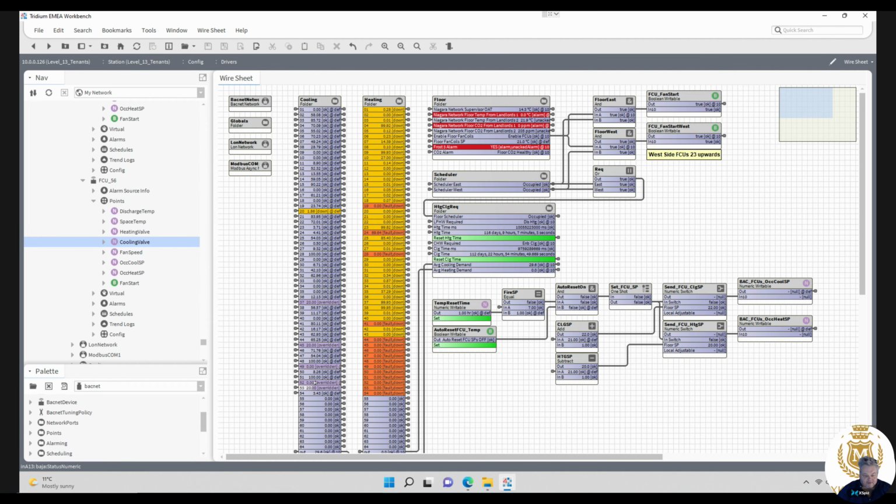And we can see that they've got some overrides, they've put some overrides in themselves. That one was down, so we know there's an issue there, and you can see now that they've overridden these fan coils. So that one, if I click on that, that's fan coil 39, 47, 51, 54 and 55. I'm not going to take the overrides off. I need to speak to somebody and find out why they've overridden them. Right, I'm going to start now on the heating one, and I'll put you on pause until I get this sorted out.